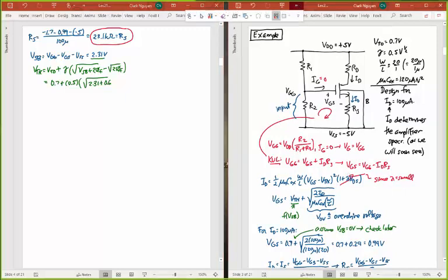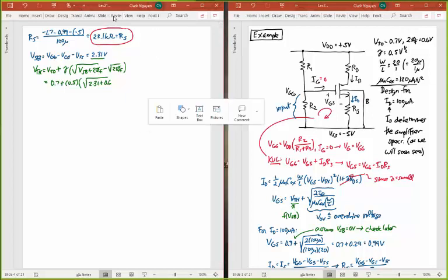So let me stick that up here. It depends on doping concentration, but that's what it ends up being. We talked about that in our physics part of the class. But going back here, so I already wrote that 0.6 volts. And so minus the square root of 2 phi f on its own, that's also 0.6 volts there.